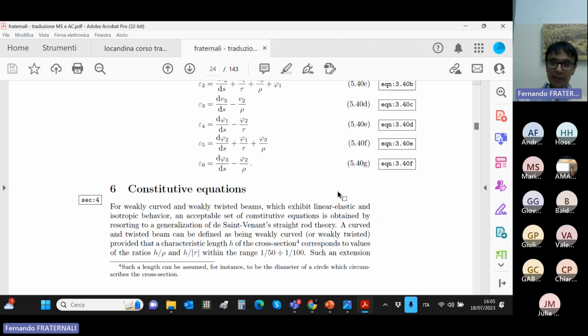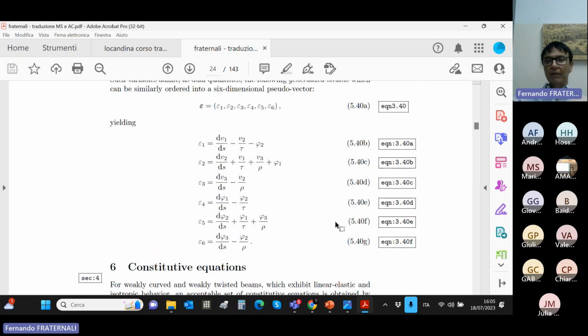We have geometric couplings between the quantities that we have seen here. So we have couplings between the axial strain and transverse displacements. We have couplings between shear forces and axial force, and transverse load and axial forces. Those are geometric couplings, and we can also have, due to those couplings, the couplings that we have discussed so far.